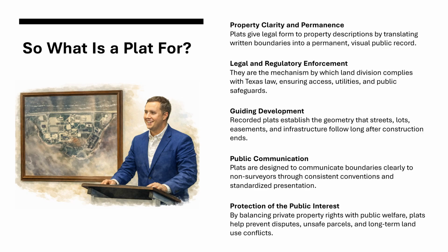Plats also exist to enforce the law. In Texas, land generally cannot be divided for sale, development, or construction without an approved plat, and that requirement is not bureaucratic filler. It is a safeguard. Through the platting process, however cumbersome, governments ensure that new parcels have legal access, that utilities can reach them, that drainage is addressed, and that development does not create hidden hazards for future owners, neighbors, or the public.